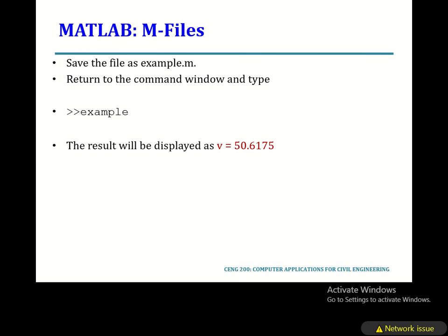In the previous, all the previous calculations which we did today, you can save them all in one file, and it will do all those things when you call the file. Okay. So calling the file very easy, right? Just type the name. Now you have to be careful about the name, like we said for VBA and other things, right? So I cannot use the name sign, SIN. I cannot use it, right? The sign is already a function.